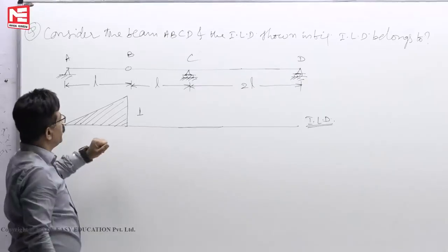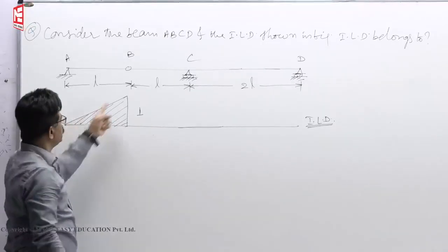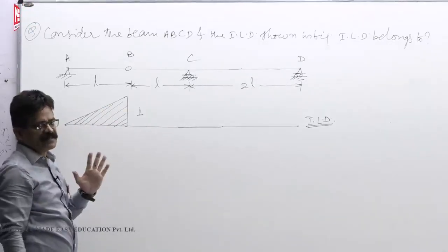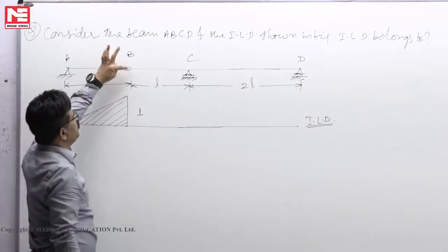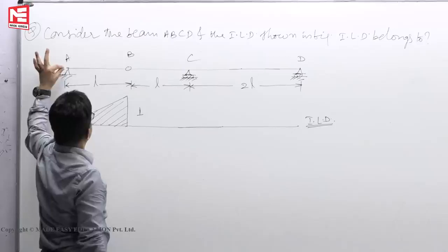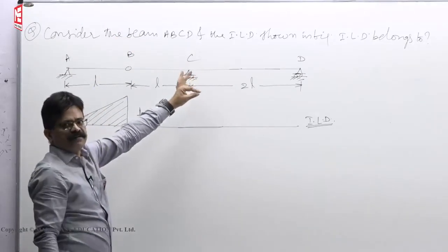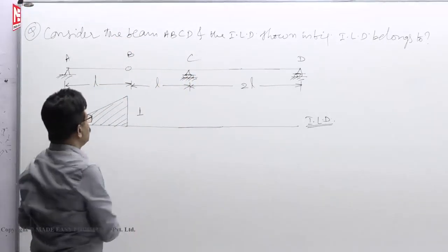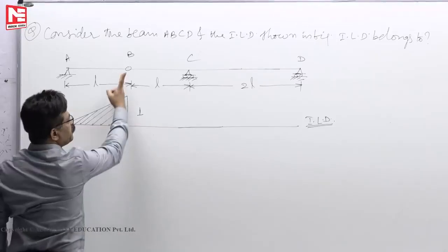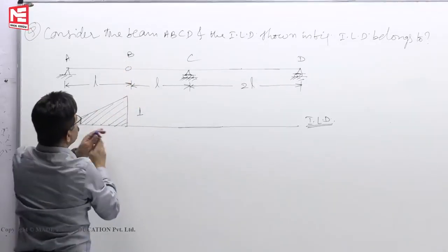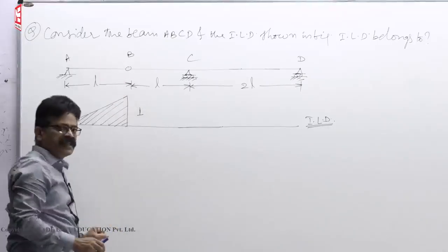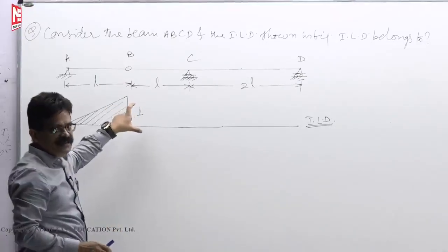Now see here, by doing what will you get this deflected shape of the beam? No support got lifted. If I assume a hinge and lift it, it will go like a triangle, so that is also not there. Then to get this diagram, I have to cut here. After cutting, the left portion is supposed to be pushed down so the total ordinate is 1.